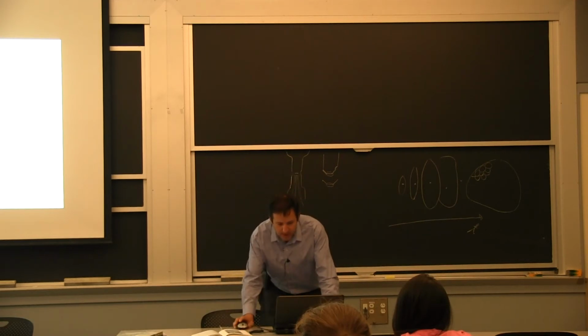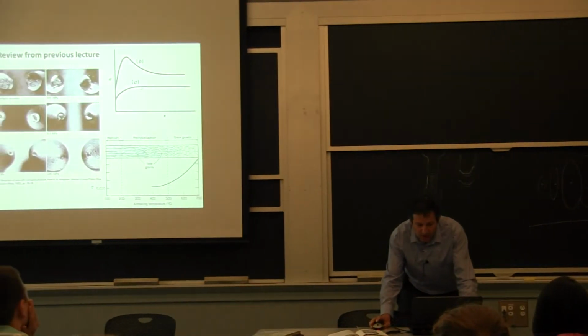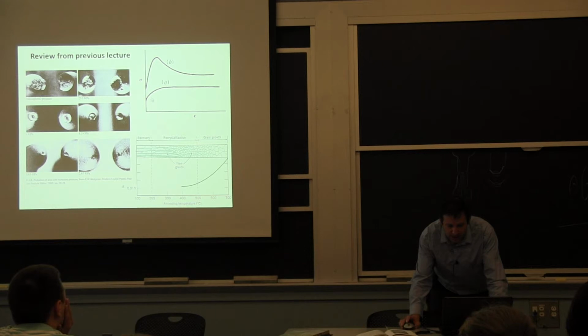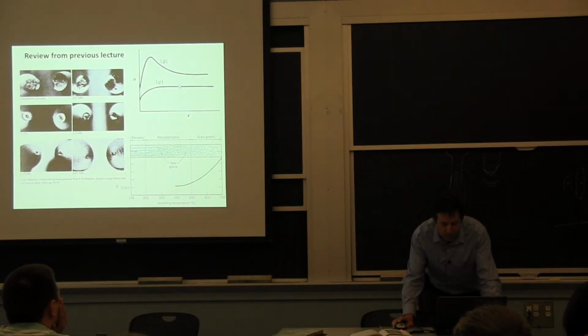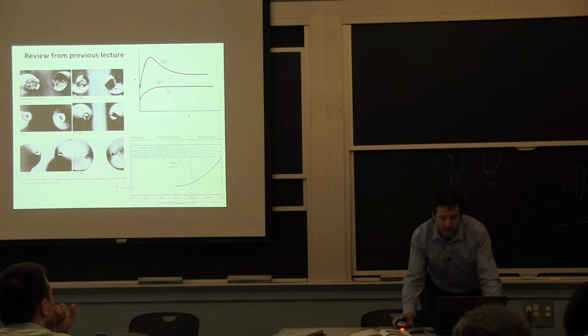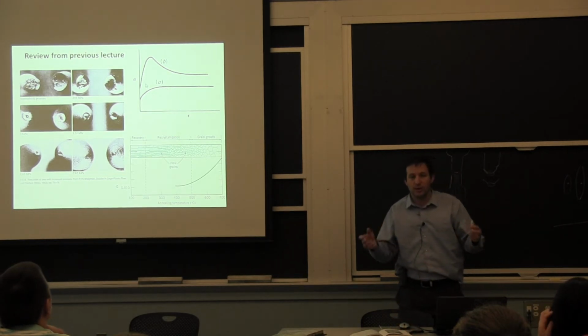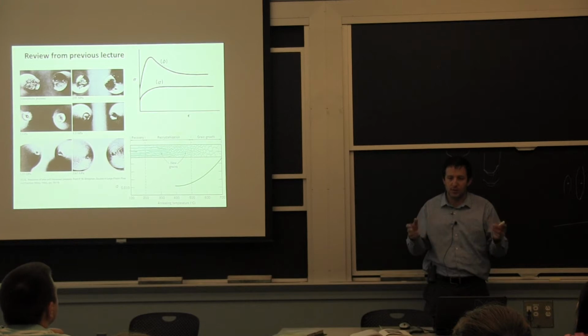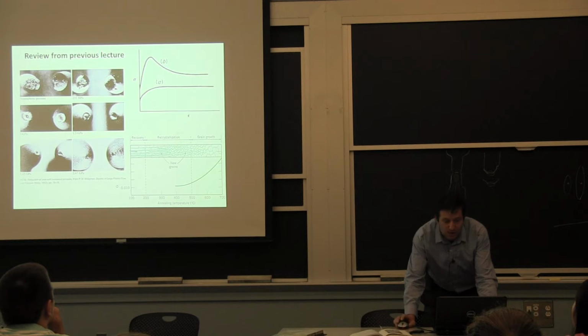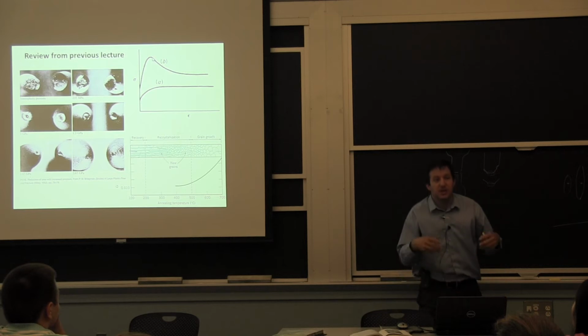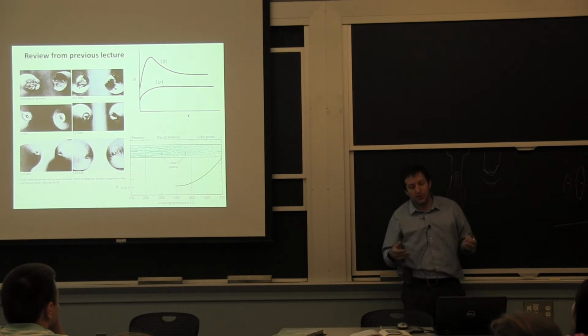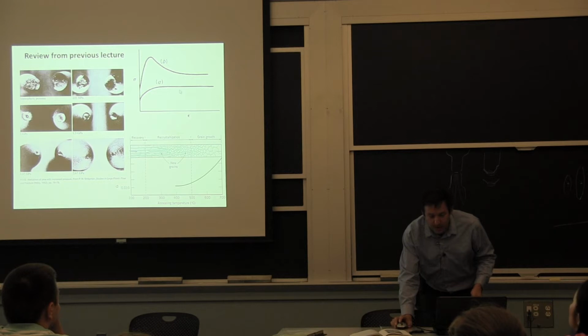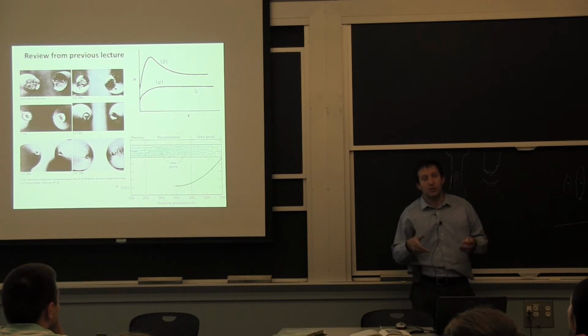So this curve here is essentially just to show, depending on how quickly you can start the recrystallization, you can have your flow stress during forming go through a steady regime right away. But there will be a situation where you start rolling and you keep accumulating deformation, and you try to recover it, but if it takes time to start recrystallization, that's where you have a peak in your curve here. So that's where speed really makes a difference. If you go slower, you're probably going to allow recrystallization to start, and you won't have that peak in force.